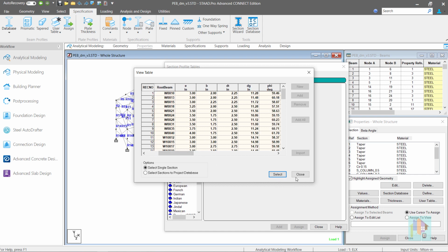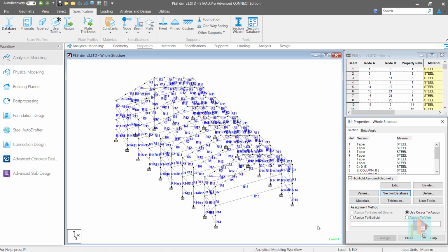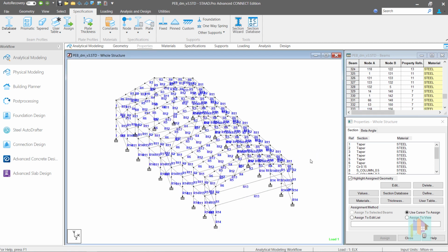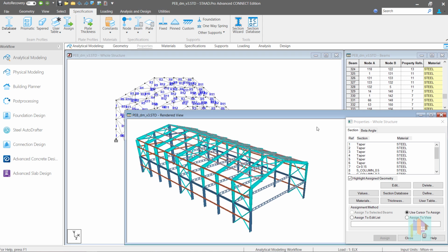If there is any axial force, torsion, MY or FZ force components, then design will not be performed. And if you want to design using any other code, it is not possible at this moment. It is also not possible to assign any custom castellated or cellular beam in STAAD as the section profile changes along the length. There is no option available in STAAD to handle this. Better to model this type of member using FEM for analysis.